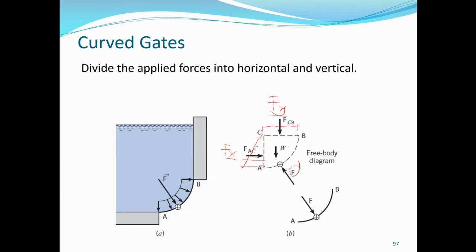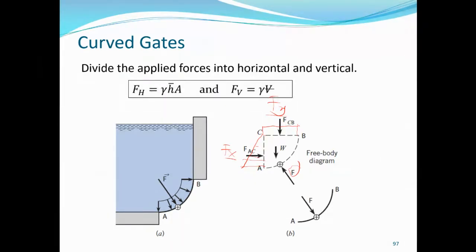So let's take an example to demonstrate the application, how to find the hydrostatic force on a curved surface. For the horizontal one, we use this. For the vertical one, we simply use the weight, the unit weight times the volume.